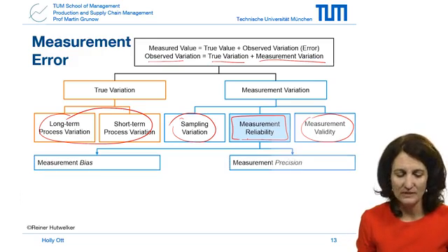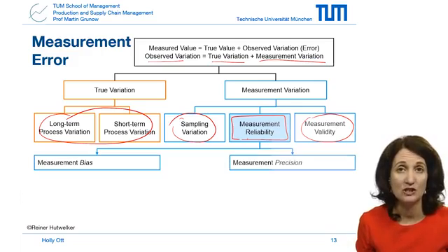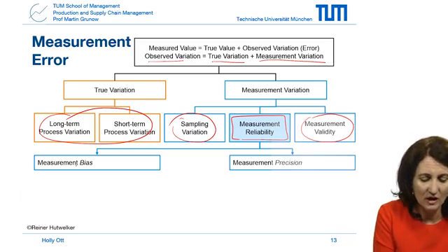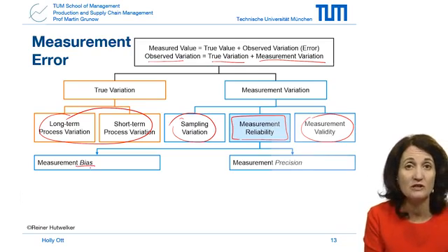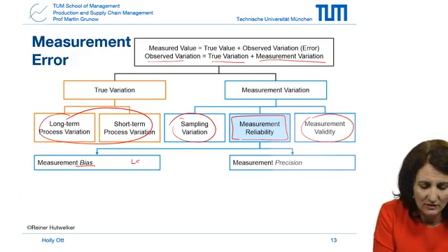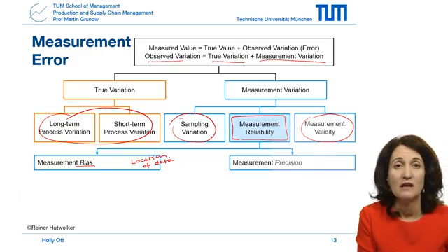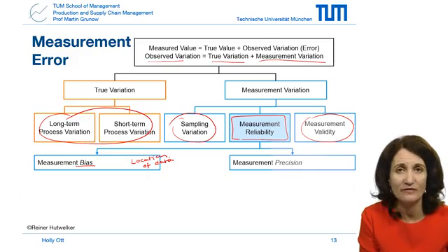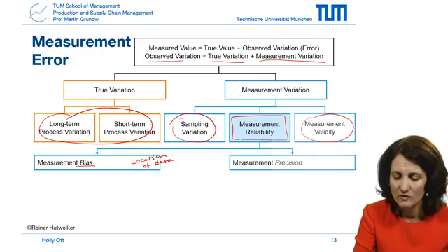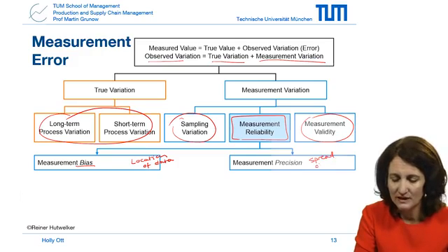The reliability then is defined by the statistical properties of these multiple measurements on the measurement system under stable conditions, and the ones that are most commonly used to characterize, as we've just learned, are bias, referring to the location of the data. Write this down, location of data, relative to a reference or a standard value. And again, bias is the deviation between the measurement and the true value, while precision refers to the spread of the data.